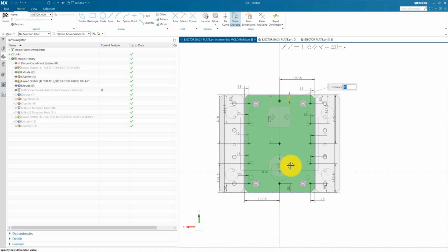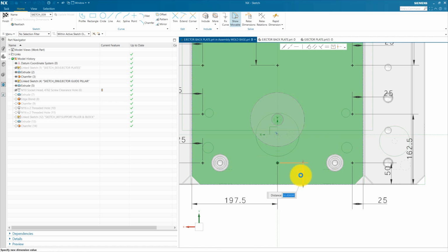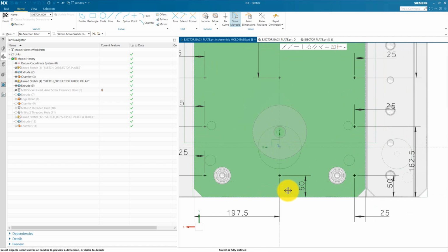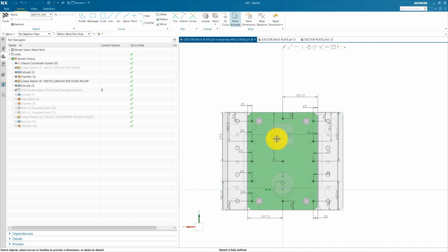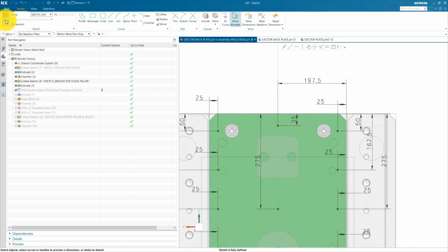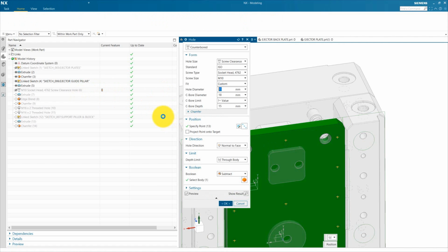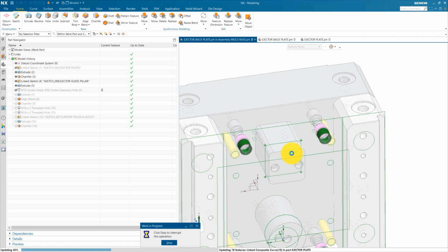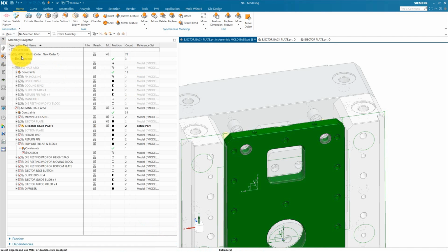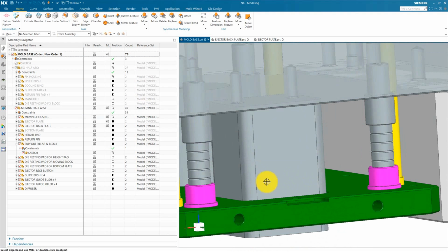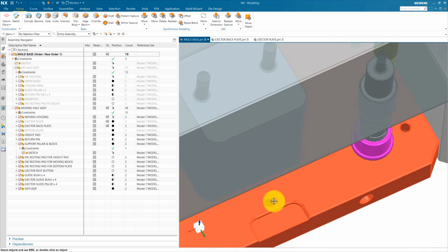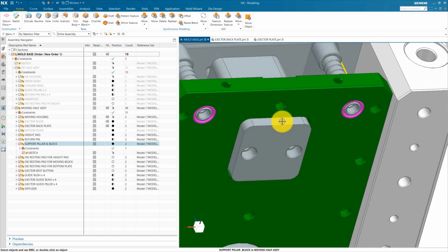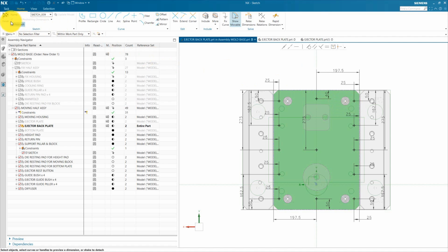This okay. Same here we are going to use 35. This is okay. There is so much space available here. And that is also okay. We can also provide more bolting holes, but we also need to provide so many things. It is okay. We only need to change this one and press it OK. This is automatically updated in our ejector plate and ejector back plate. So that is the advantage of working in parametric. Here, there is no problem, but we can also go a little bit inside. We use 40.